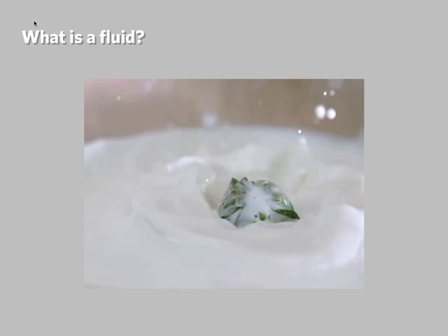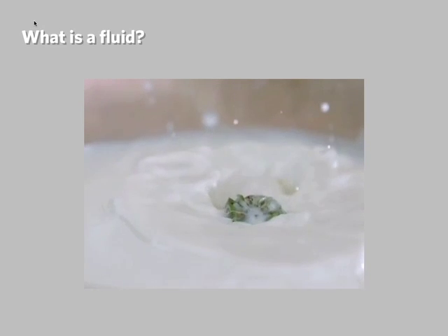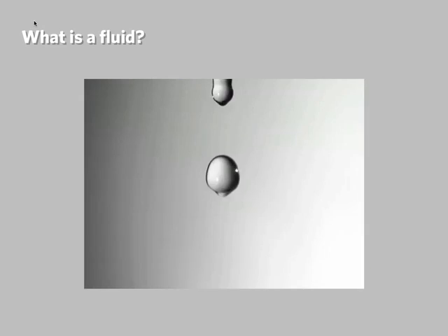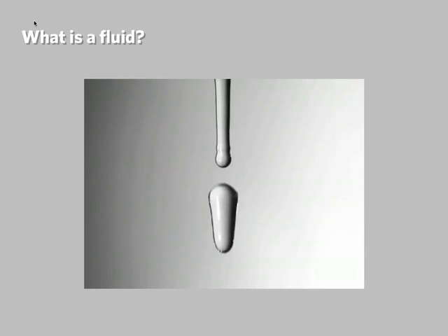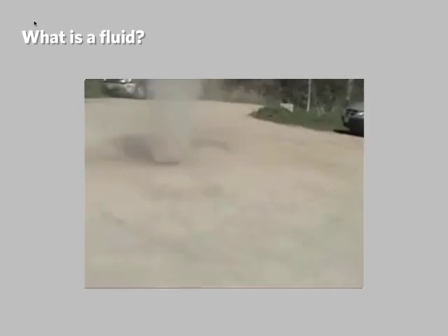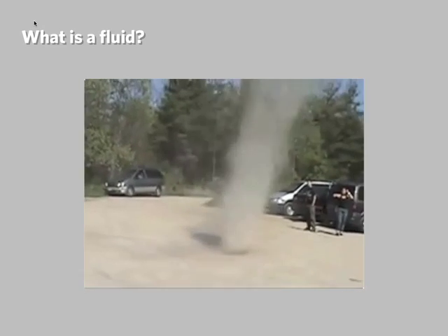Now, there was a very famous professor at MIT called Edgerton who was able to capture that effect with a high-speed camera. And we want to try to understand it in engineering terms. What causes a jet of fluid to pinch off like this? Well, there's a surface tension that causes the pinching off, because there's a high pressure in the thinner areas, and that high pressure causes the fluid to move away from the thinner areas once an instability sets in.